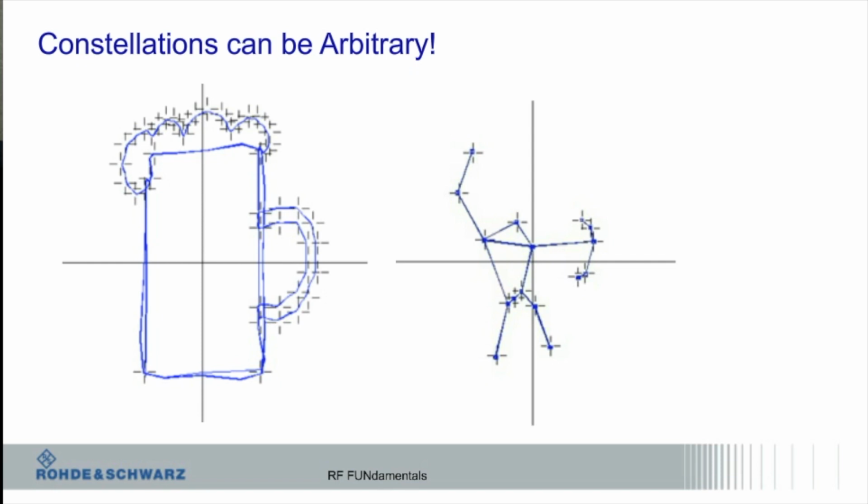But to some extent, it really depends a lot on how much it's moving. You can put frequency tracking on. If you're in a phase noise mode, within a reasonable range, it should be tracking the frequency of the DUT. A phase noise analyzer is designed to work that way. It actually has two different bands for measuring that, so it can deal with a lot more error. But basically, if you have frequency tracking on, it should do it. And if you have a problem, you're more than welcome to call me, and I can help you with it. You're welcome. Okay. Any other question?